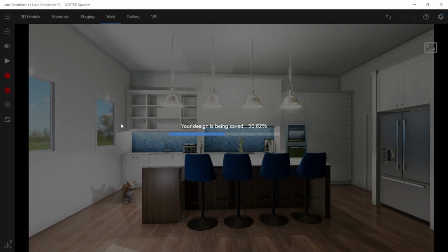all of the viewpoints will be converted into pictures. So when I'm saving right now, I don't remember, I probably had 10 viewpoints. So right now I'm creating 10 renderings of my project. So that's very, very quick to create the pictures. What's really nice with that as well is that every time you save, the software will delete the pictures you had and replace them with new ones. So if you make any changes, you don't need to go yourself and delete any of the pictures that you might have saved there.